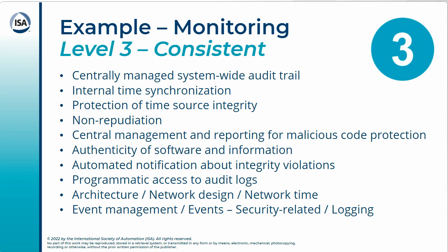And this idea of the programmatic access to audit logs, this means that automated systems, centralized management systems, can either pull logs from devices with, say, like WMI calls to Windows systems, but they can also receive pushed notifications from, say, syslog from your network equipment, or syslog from different PLCs or devices.